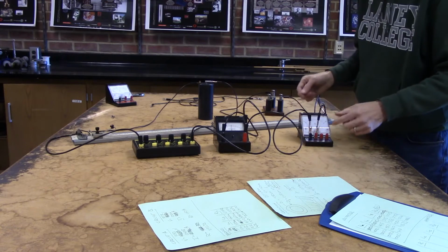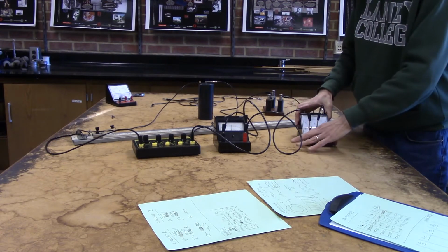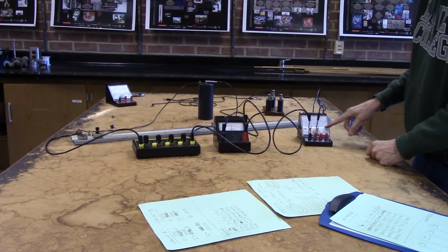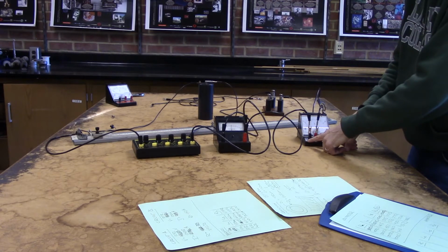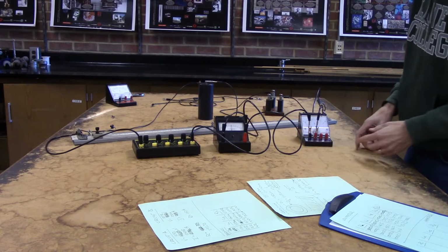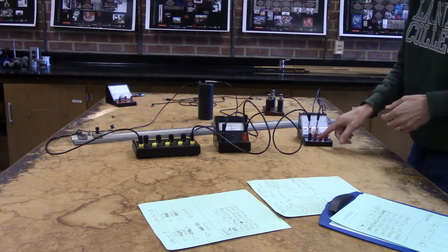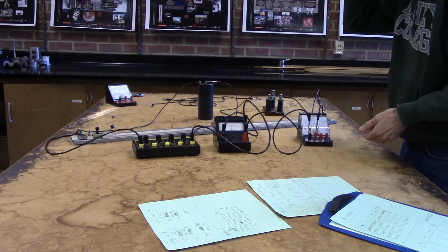Now, the voltmeter is no longer being used as a voltmeter, it's just a resistor. So I'm finding out how much resistance this voltmeter has. Now, I've got it at the lowest voltage setting. There's a range of different settings. There's a 3 volts, 15 volts, 300 volts. The lowest resistance should be for this 3 volt setting.